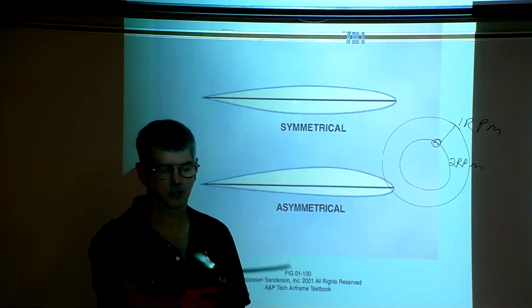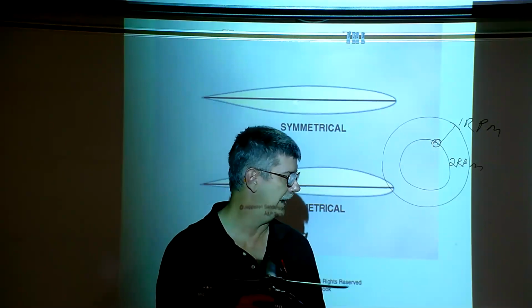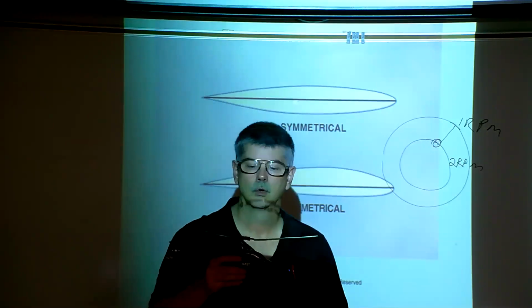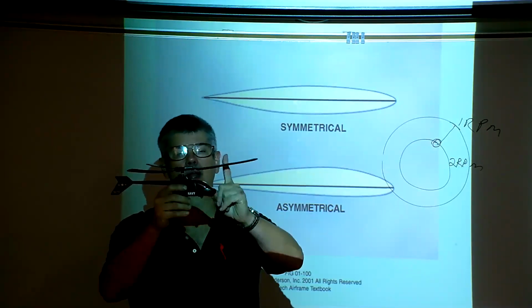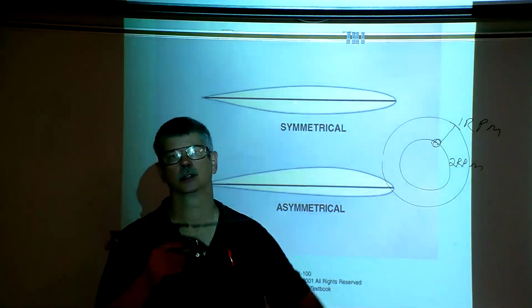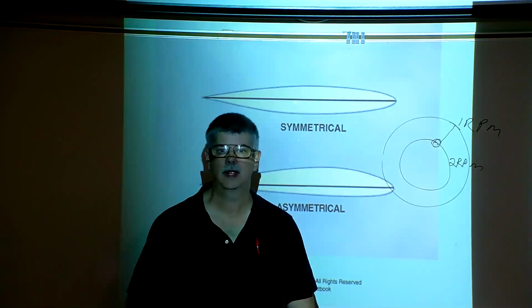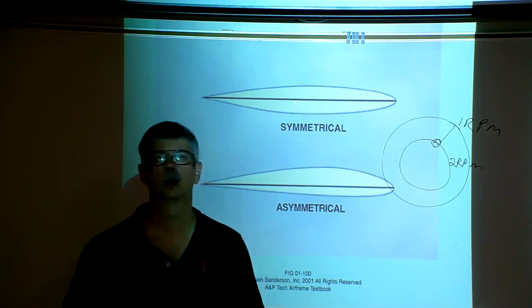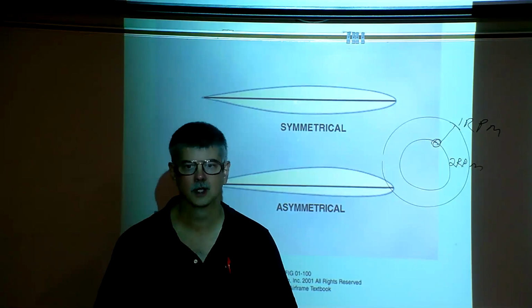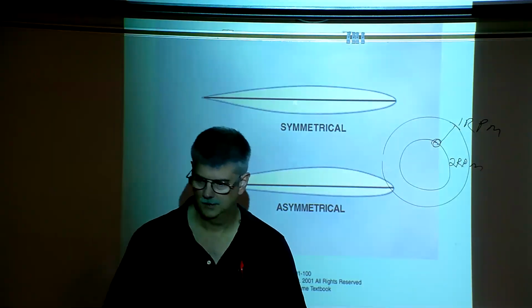When we get close to the ground within one diameter, you probably can't see that, okay? What happens is the air coming down hits the ground and has to slow down to make a turn. Because the vertical velocity of the air has decreased, the angle of attack of the rotor blades has increased, thus providing more lift. Are we good there?